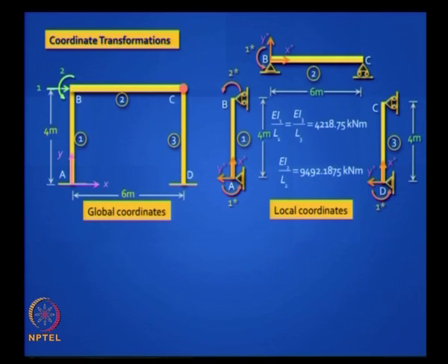Okay, now look, the change we are making now compared to the previous problem is, in elements 2 and 3 we knock off the rotational degree of freedom at C. So the size of your stiffness matrix, your TD matrix, reduces. You have 2 degrees of freedom for element 1, no change there, and you have only 1 degree of freedom for elements 2 and 3, and you should release at the right place where there is the moment release, there is the hinge, internal hinge at C. It matters little whether the hinge is internal or at a support. Clear? Okay.